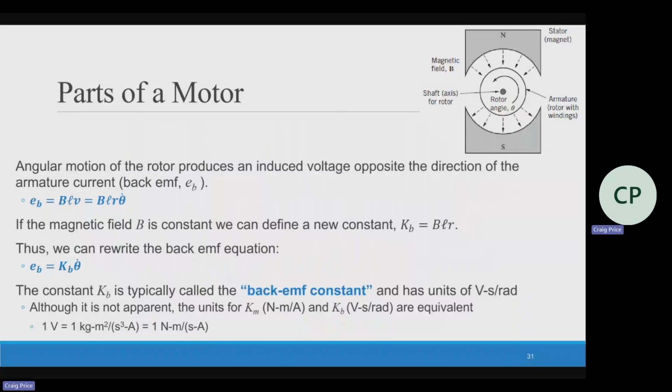The field coils can be connected to the rotor windings in two different ways: parallel or series. The result is two different kinds of DC motor construction: a shunt and a series motor. The series wound motor has good starting torque, but its speed drops drastically with the load. The shunt motor has a low starting torque, but it is able to run almost at a constant speed, irrespective of the load acting on the motor.